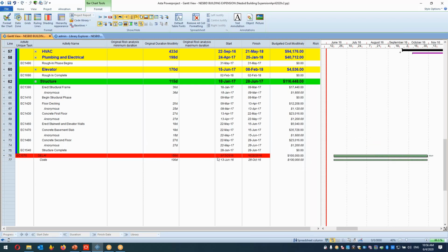If there are 100 days of delay, it will be 100,000. So you can model the delay task, and its duration can be calculated automatically if you create a special link to the project end as an intermediate or buffer task, because Powerproject has an extra task and the delay will be calculated automatically. So if we have 10 days of delay, we will have to pay an extra $10,000. So you can also model it and integrate it with the budget.